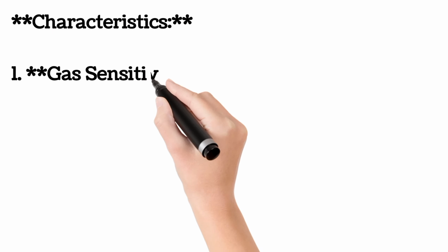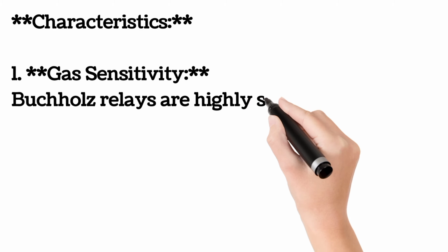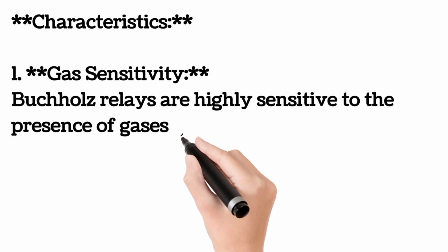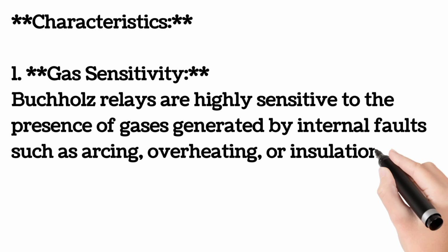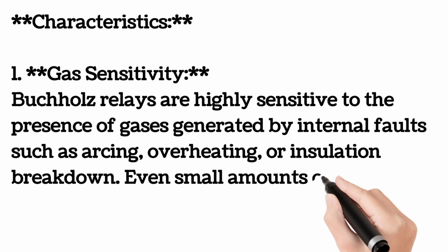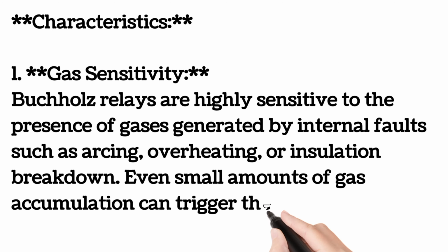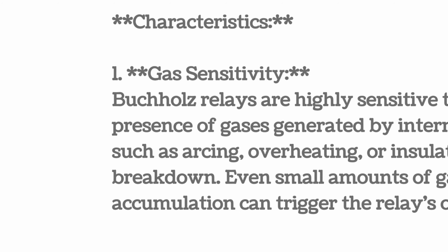Characteristics. 1. Gas sensitivity. Buchholz relays are highly sensitive to the presence of gases generated by internal faults such as arcing, overheating, or insulation breakdown. Even small amounts of gas accumulation can trigger the relay's operation.